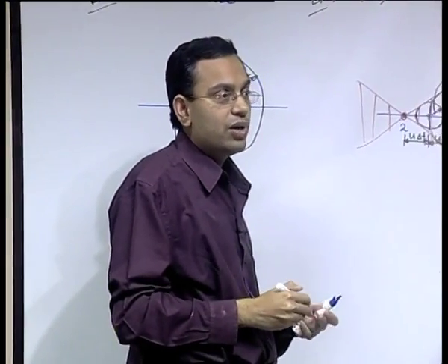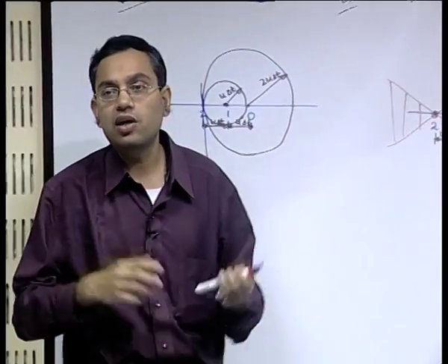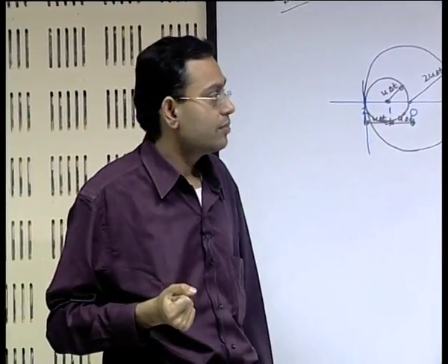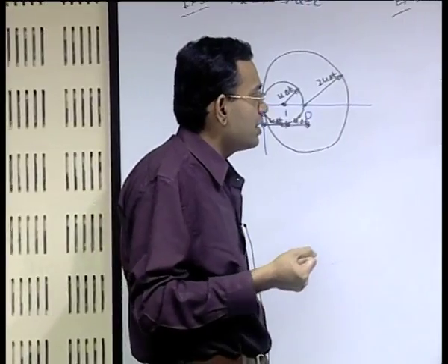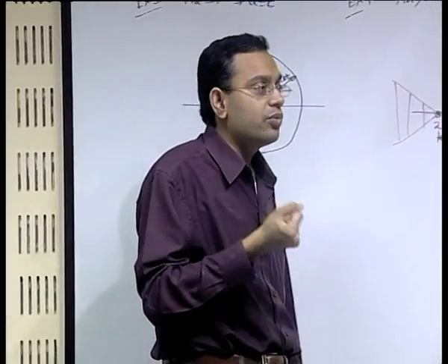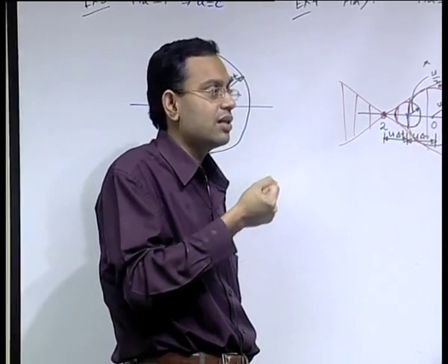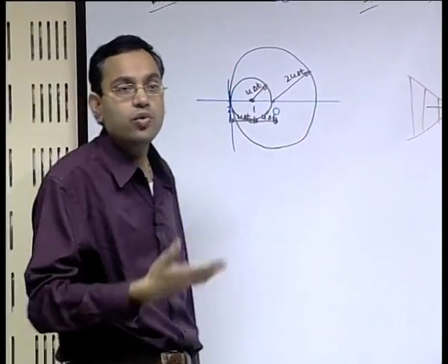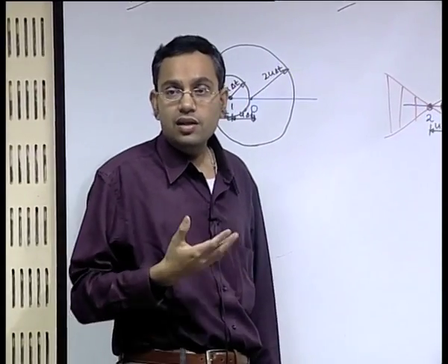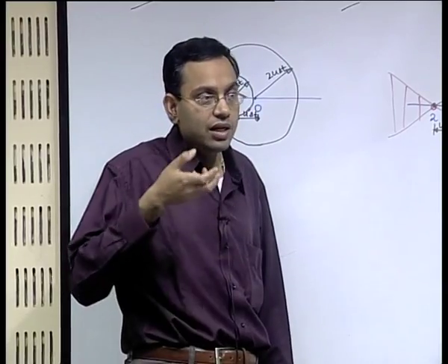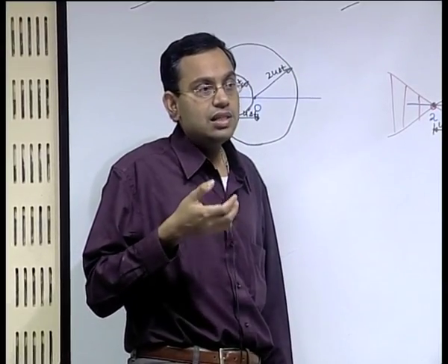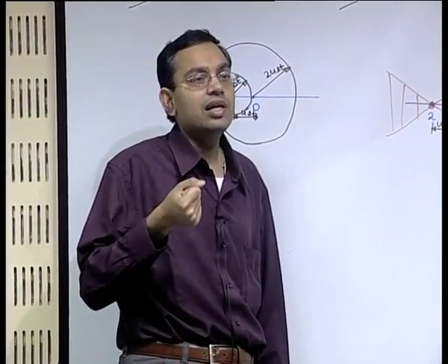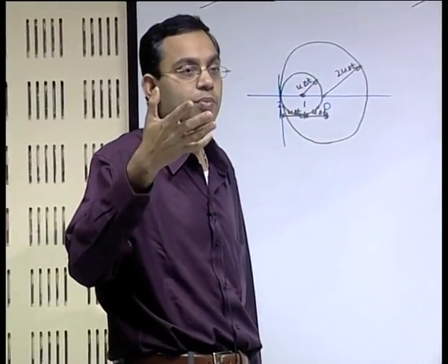So, the question is, why do you have such discontinuities in compressible flows, or strongly compressible flows? The reason is that if you have hyperbolic equations which are valid in cases of highly compressible flows, for example supersonic flows, then if you have a disturbance, the disturbance propagates at a speed which is not matching with the speed of the source propagation itself.